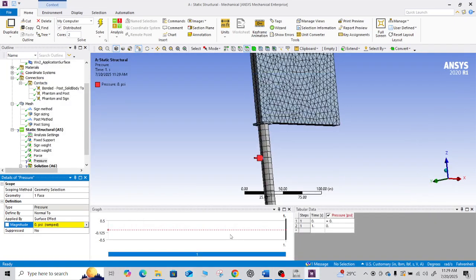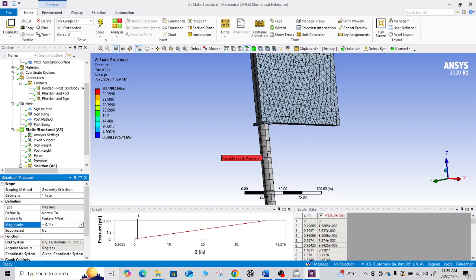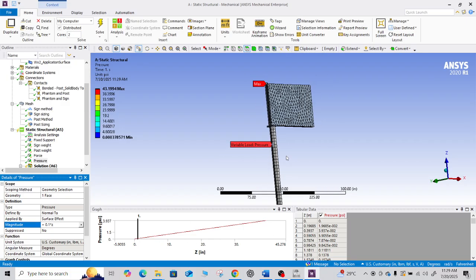So you have to input an equation. It's similar to how you input an equation in Excel. You have to use an equal sign, and then 0.1 times z. It is in the z direction. Okay, so now if you apply, Ansys automatically, you see, calculates all the forces, the varying load. So if I rename that, it would be varying load.